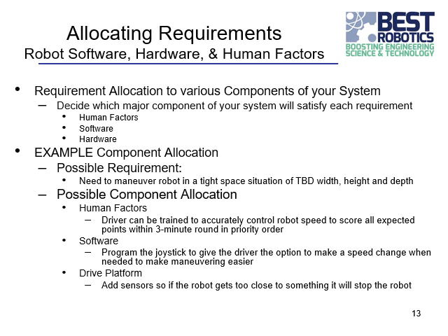So a little bit more background as far as design. You've got requirements that you know from the rules that you need to do, but then you need to say, is the software on the robot going to handle that? Is the hardware in the robot, or is the driver or the spotter going to be able to accomplish that? They all need to play together, and if you've decided this is something your robot needs to do, you need to say where am I going to allocate, assign that capability? Is it going to be done in software, hardware, or your driver and spotter?